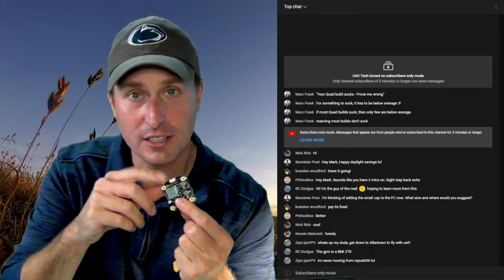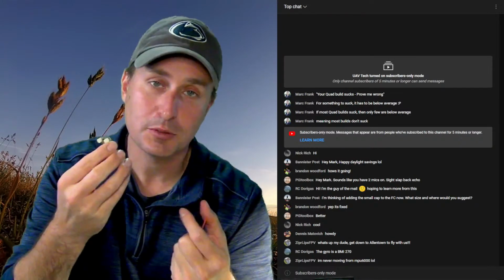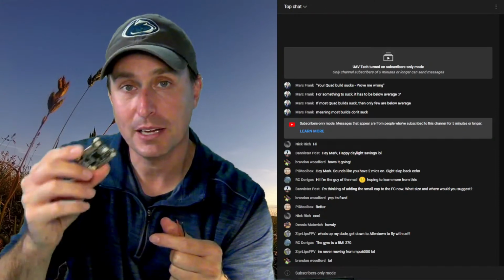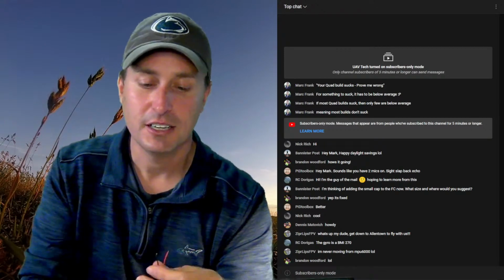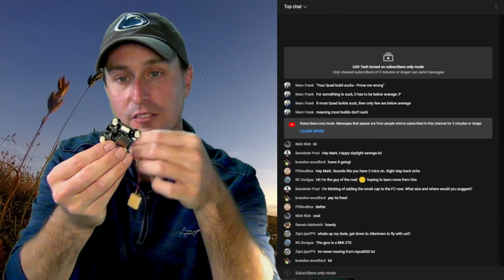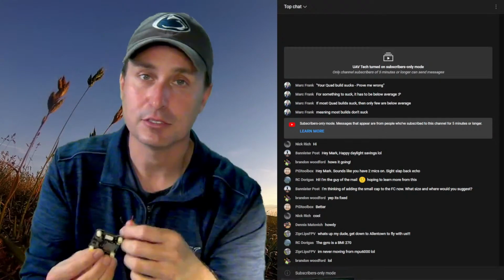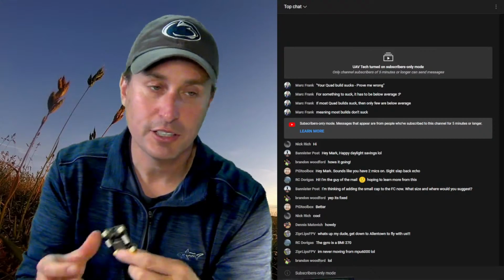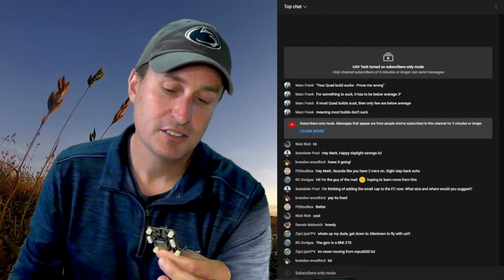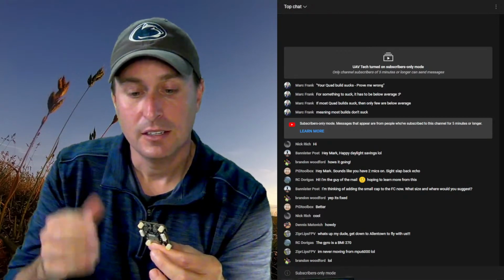Most people have a 4-in-1 ESC, and if you desolder the VBAT pad, which is what powers the flight controller, and then you power this up and hook this up to the flight controller, red goes to VBAT on the flight controller, and black goes to ground, of course. Then your flight controller is now powered by a separate battery. So it's just like a test flight. It's not that hard to depin the one pin and solder this up.